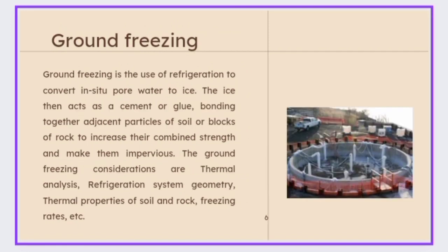Now coming to the ground freezing technique for ground improvement. It is the use of refrigeration to convert in situ pore water to ice, in simple words. The ice then acts as a cement or glue, bonding the particles together to increase their combined strength and make them impervious. The ground freezing considerations are thermal analysis, refrigeration system, geometry, etc.